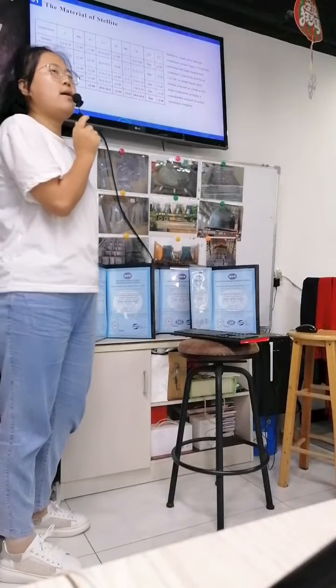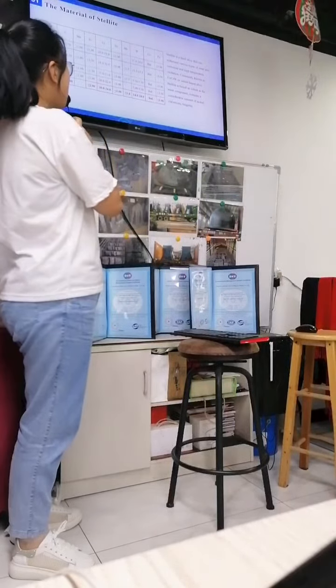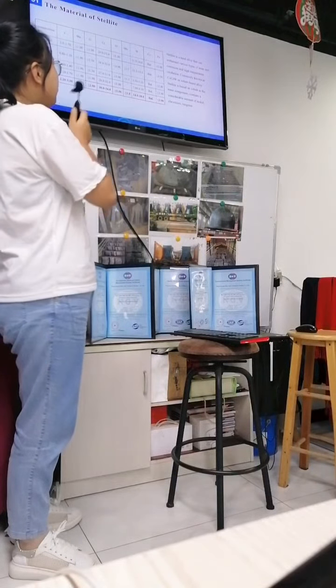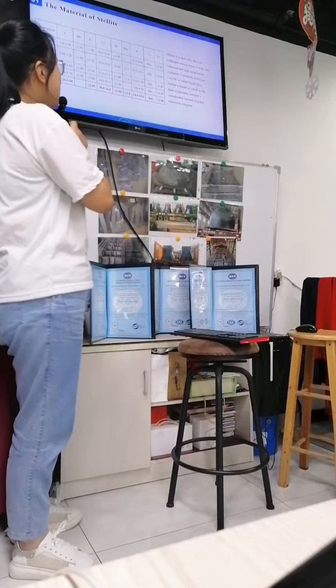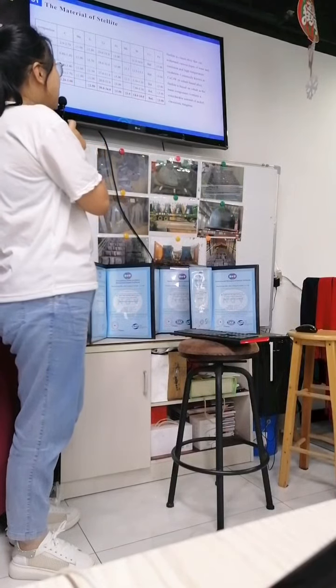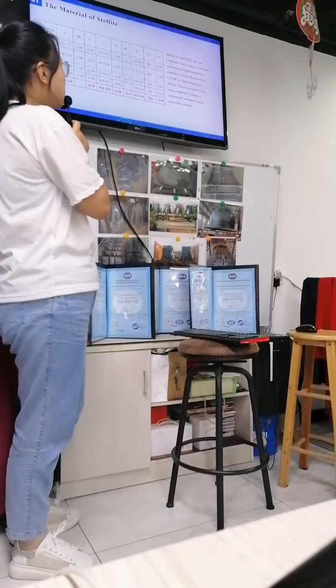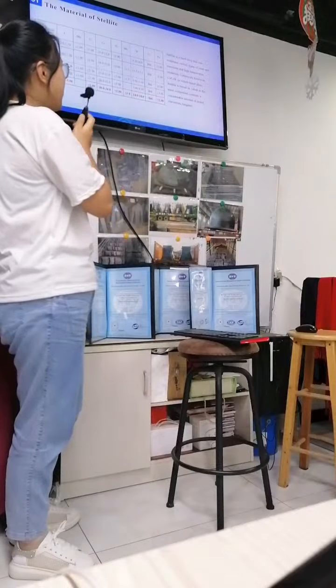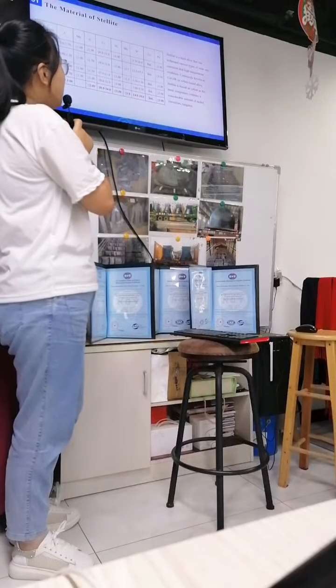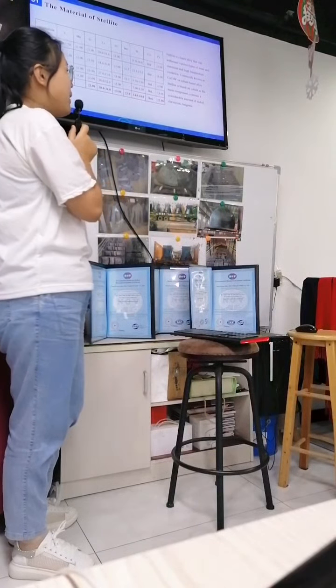You can see this table is the chemical composition for C9, such as C9-3. For carbon is 2.0 to 2.7%. For manganese is less than 1%. For chromium is 29 to 33%. For tungsten is 11 to 14%, and the cobalt is balanced.